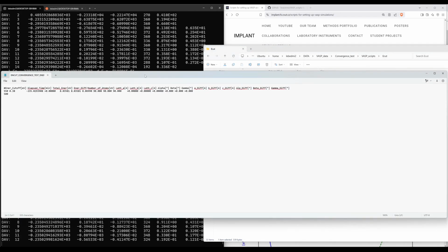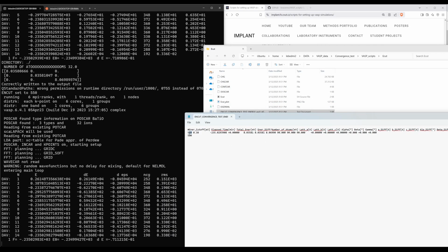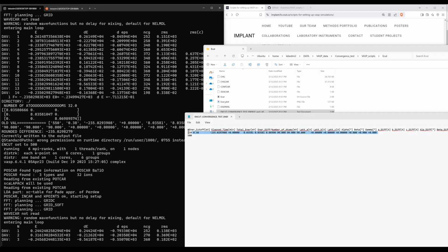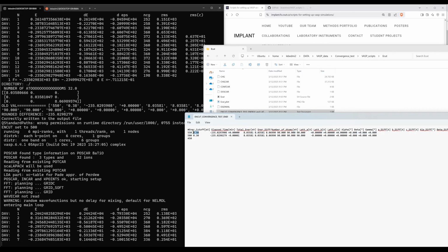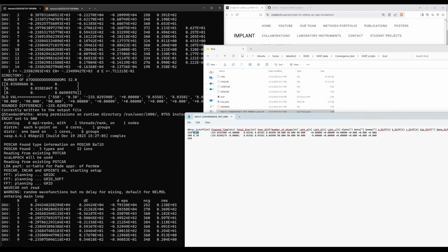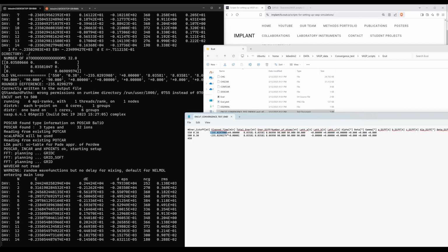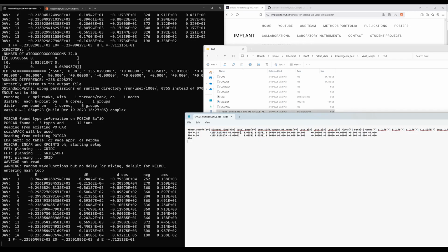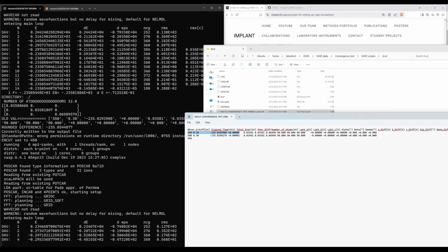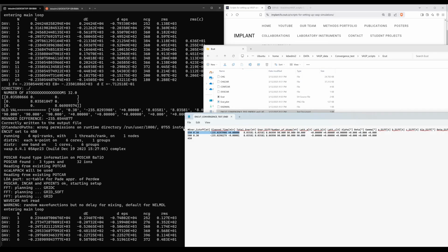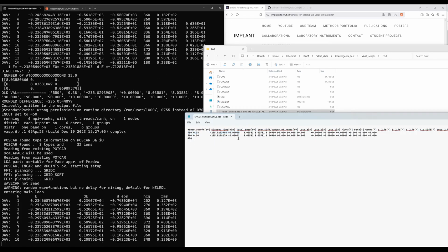So if I open it, it mentions the current ecut parameter, the total simulation time it took to compute for this parameter in minutes, then the total energy, and this one, the first value, is set as a baseline value to which all other lower ecut parameters are compared.